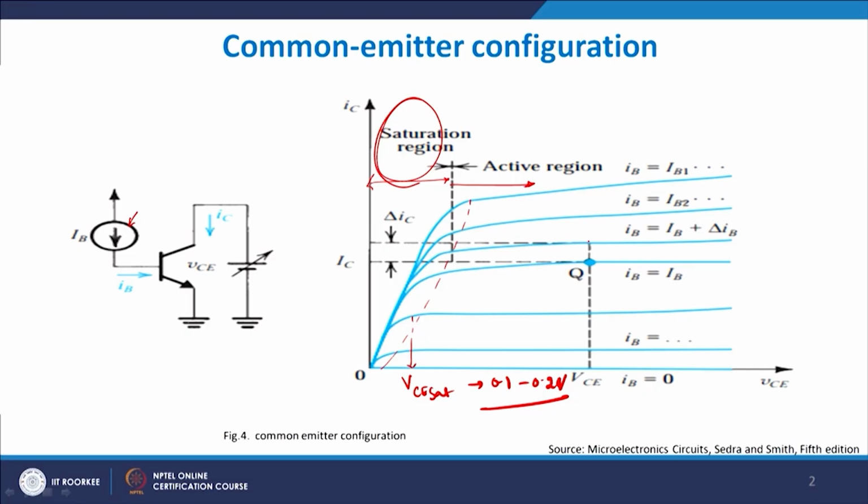Also, if you look very carefully, you have this IB value of the order of a few microamperes, whereas the collector current is of the order of a few milliamperes, and you need to know this basic fundamental principle. Now let us look at one small point before we move forward: even without any drastic mathematical formulation, I can show you that we are indeed doing a small amount of amplification here, and I can show roughly how by this diagram.